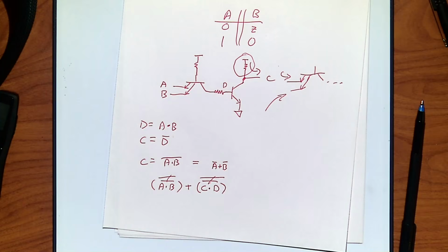Remember, every gate adds latency. So if you give me more inputs and I can calculate your whole thing in one transistor, that's going to be fast, low latency. We like low latency, right? That gives you quicker circuits. But a quicker circuit means potentially a lot more current coming in. And what happens if I get too much current? It heats up, lets the magic smoke out, it's all done. We don't like that. So we could say there could be a problem here. Ideally, I'd not like too much current in the line.